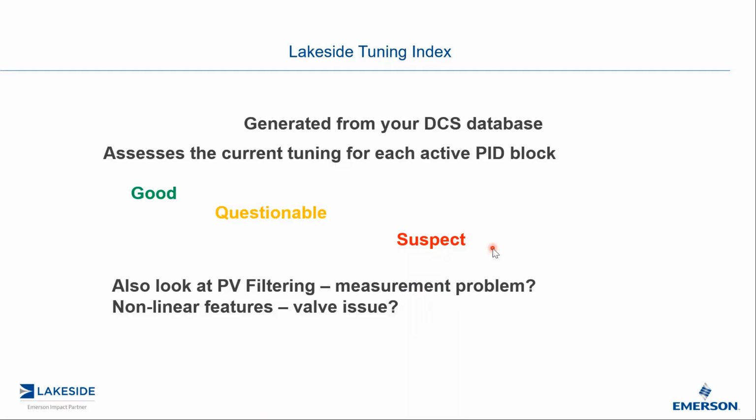I also look at PV filtering, which falls into my next session in April. We're going to talk about PV filtering and PV dampening. If I find that a particular control loop has an excessive amount of PV dampening, it might be an indication that there is a measurement problem. That's how we sweep it under the rug and try to hide the problem. PID algorithms can also have what I call nonlinear features, like dead bands and things like that, which could be an indication of a valve-related issue.